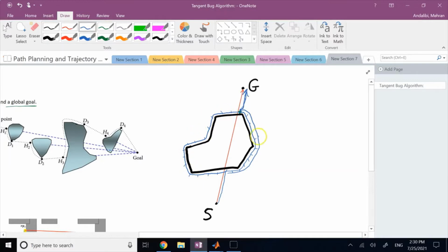So it's one extra round of motion around the boundary before making any decision, right? So you see clearly how much it has to go. It's like this, going all the way, coming back, and then this extra amount to go back to a point that you already visited. But you make an informed decision because you have all of the distances. So this is called the Bug 1 algorithm, okay?